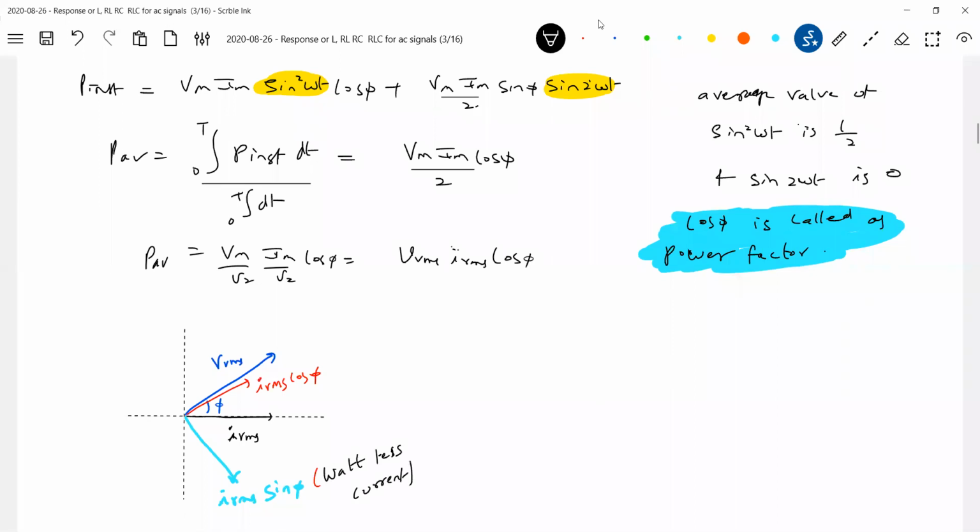Now you should not laugh. So actually, which current is flowing? I, IM, IRMS, IRMS cos phi, IRMS sin phi. A student must really ask these three things, sir. What is this instantaneous current? That will vary sinusoidally. Among the maximum, RMS, RMS cos phi, RMS sin phi, sir, which currents are flowing? Actually, this is the current which is flowing. This we are expressing in various ways. This is the only current which is flowing in the circuit. And when will it be equal to IM? Twice in one cycle.